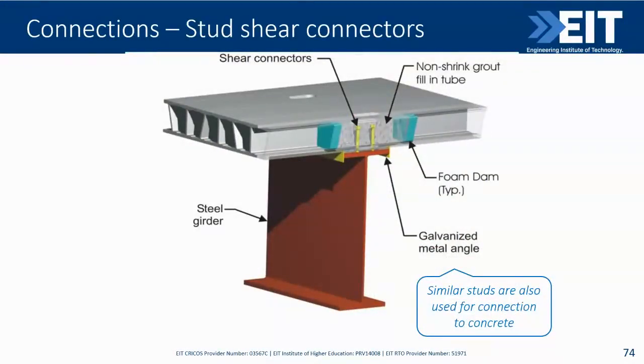And here is one more example of a hybrid structure, presenting a combination of steel girder and FRP deck. For anyone familiar with steel-concrete composite construction, in this case the concept of shear stud connection is used.